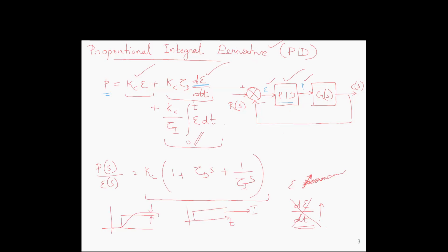This difference or deviation from the reference or the set point is the offset. Whenever you use a proportional controller or a proportional derivative controller, you often end up with offset. So if an offset is tolerable, then we can use a proportional controller.